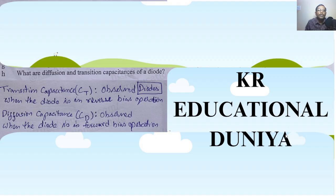Next question. What are diffusion and transition capacitances of a diode? This comes under the PN junction diodes unit. Okay, so what is transition capacitance? It is observed when the diode is in reverse bias condition. When the diode is in reverse bias condition, the depletion region layer behaves as a capacitance. So that capacitance behavior is called transition capacitance.